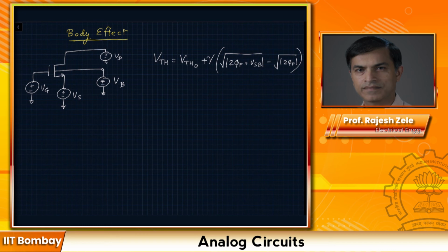So just like the drain current changes because of potential difference between the gate and source, you could also say that the drain current changes due to potential difference between body or bulk and source, since VTH is changing. We can call the body or the bulk also a gate. However, it's called a back gate. So body is also called back gate.